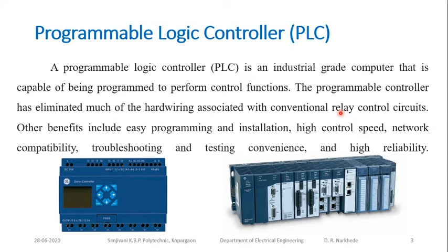Okay, so over a period of time, they found the device called PLC. This is the programmable logic controller, in which the internal logic is performed in the form of programming, and the most commonly used language for programming is the ladder logic program. PLCs come in various sizes. This one is commonly used for low input, less number of input outputs. These are called brick PLC, micro PLC, or mini PLC, and these are the modular PLC. So in the brick PLC, the controller, input terminals, output terminals, or input modules, output modules, display, memory, everything is in the same unit.